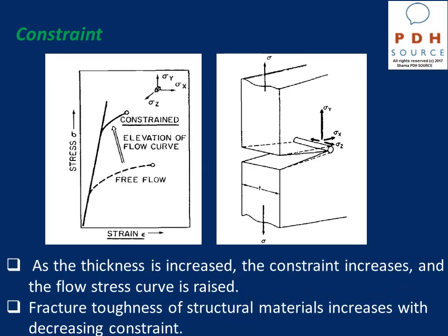So we can say that as the thickness is increased, the constraint increases, and the stress strain curve is going to be raised. So this is the case of constraint, but with limited ductility, of course. Also, fracture toughness of structural materials increases with decreasing constraint.